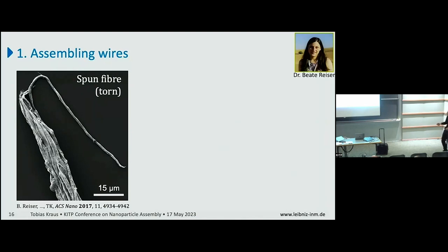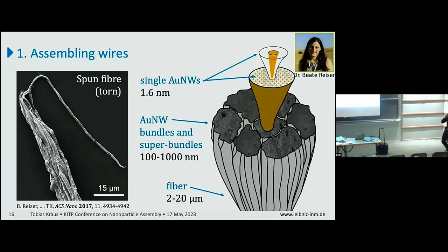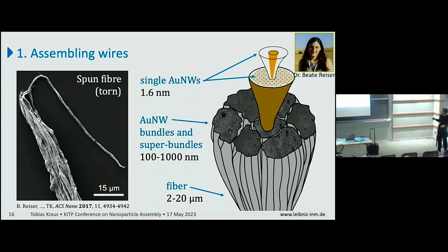And that's also the case for these fibers. If you look at it more closely, you'll find that the way they form is by first bundling at this relatively small scale of the single wires, which make these densely packed, triangular packed fibers, or bundles, I should say. These then form larger bundles and larger bundles, you may call them super bundles, until you arrive at this fiber with many micron in diameter, depending on which concentration you chose and how large the nozzle was.